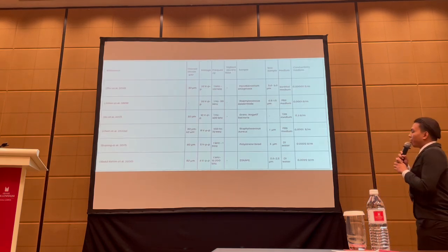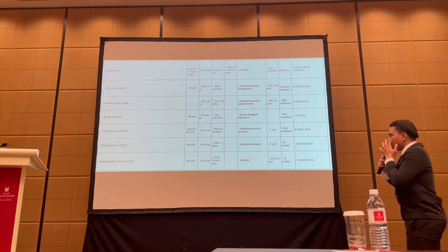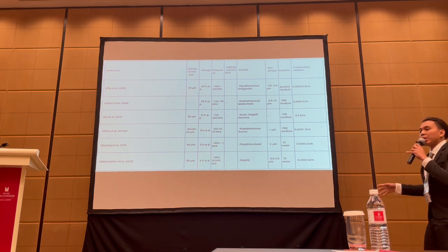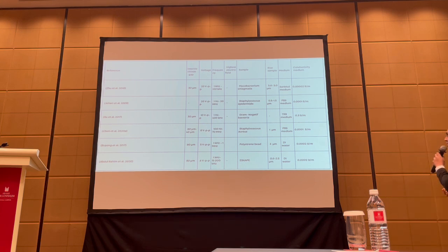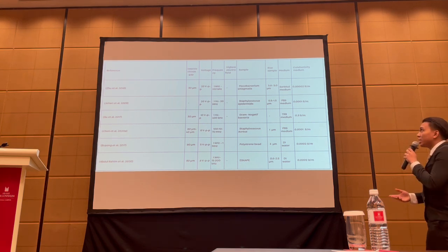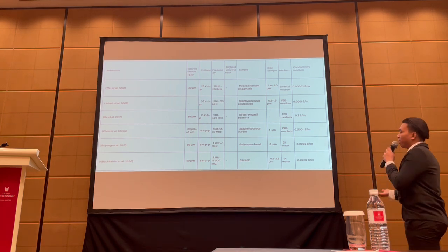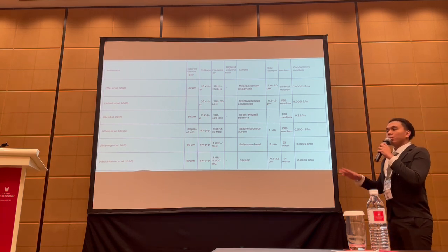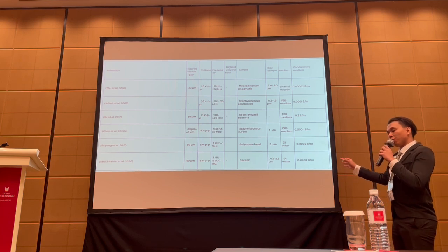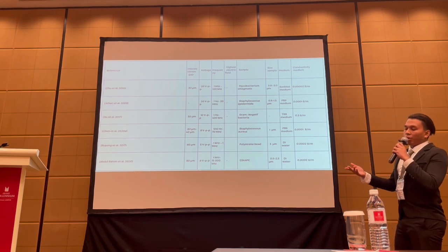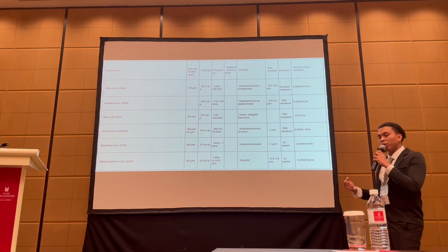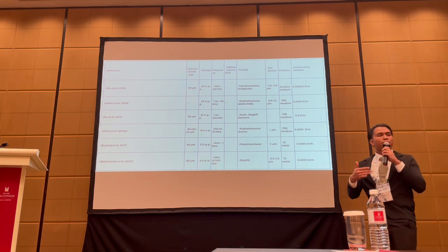So this is our reference based on past DEP research. As you can see, it's not consistent when it comes to dielectrophoresis. Different inter-electrode gap, different voltage, different frequency, different sample obviously because we need to test every bacteria. Different sample size and different medium. So as I said, the three main components just now actually depend on the DEP itself. So we have to find the biological properties of this bacteria.